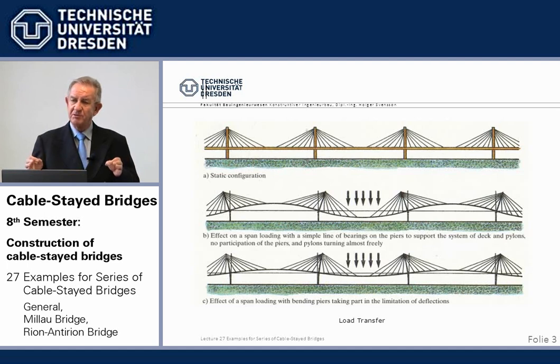The one problem is how to stabilize the tower tip, because there are no hold-down backstay cables. And the second is, because of their increased length, how to cater for the changes in length in the beam due to temperature, shrinkage and creep and so on.